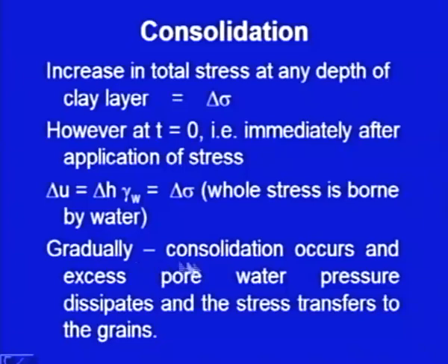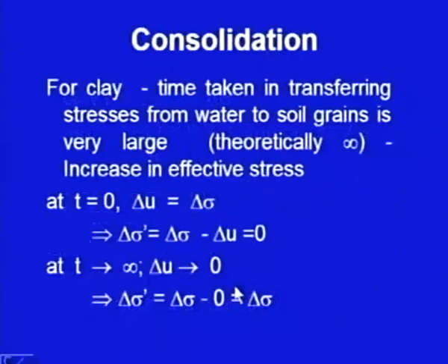Gradually the consolidation will occur, this excess pore water pressure will dissipate and the stresses will transfer to the soil grains. Theoretically, the time taken in transferring these stresses from water to soil grains is very large. Theoretically, it is infinity. So, at time t equal to 0, the increase in the excess pore water pressure is equal to the total increase in the total stress.